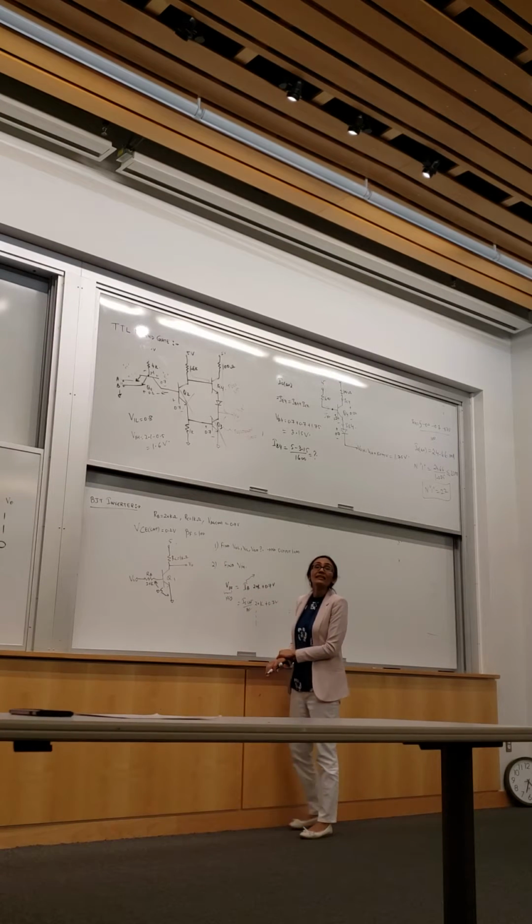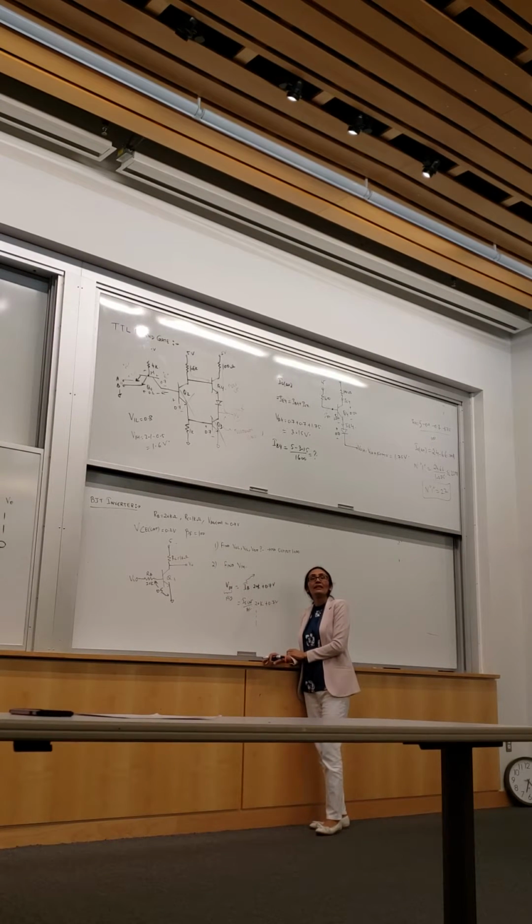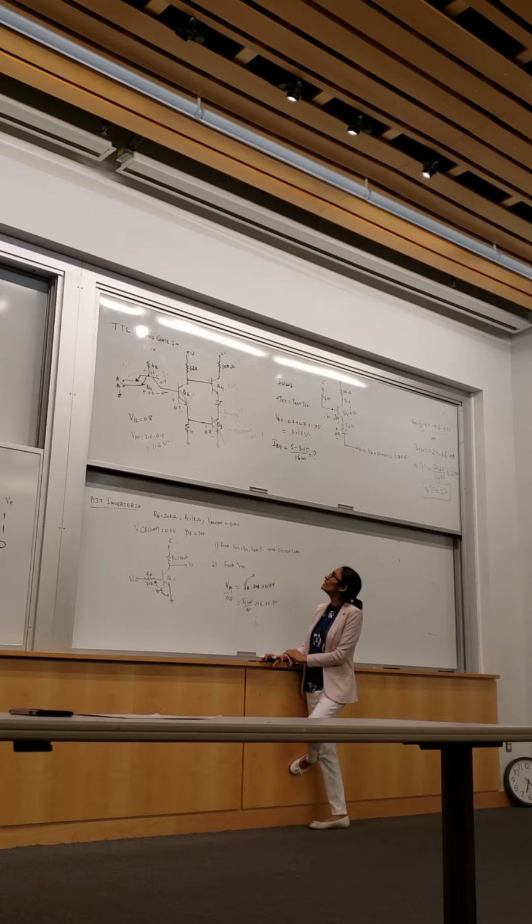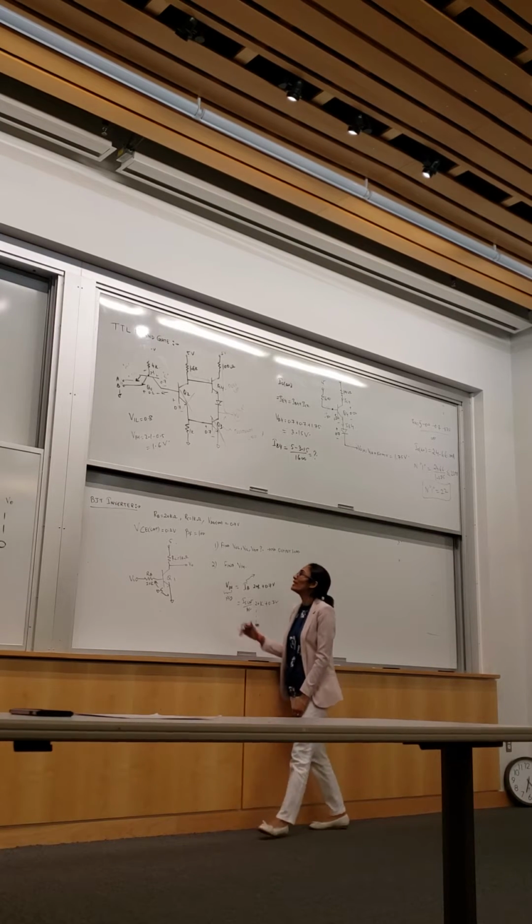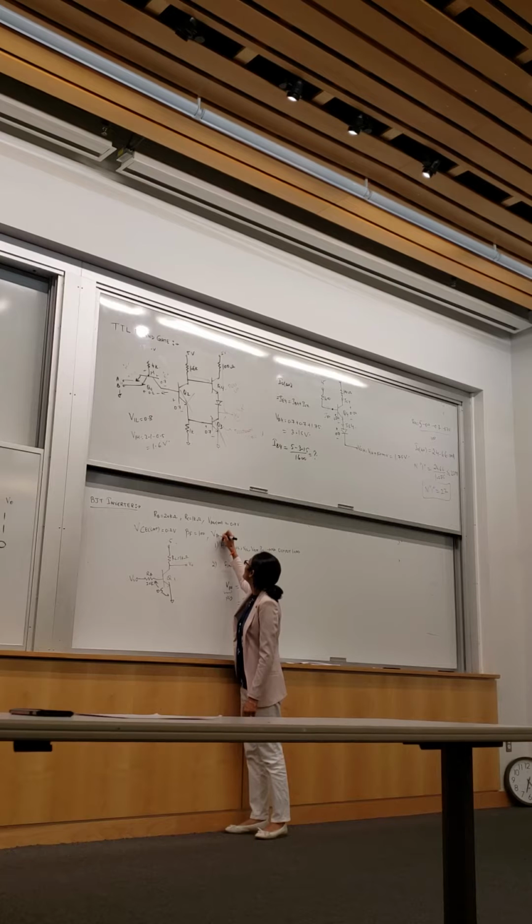So that 0.5 volts, is that an assumption that we're making, or are we getting that from subtraction that I'm not remembering? We're not making an assumption. V_B cut-in is 0.5 volts. Okay. You should know that by now. I'll just provide that if I give you this problem.